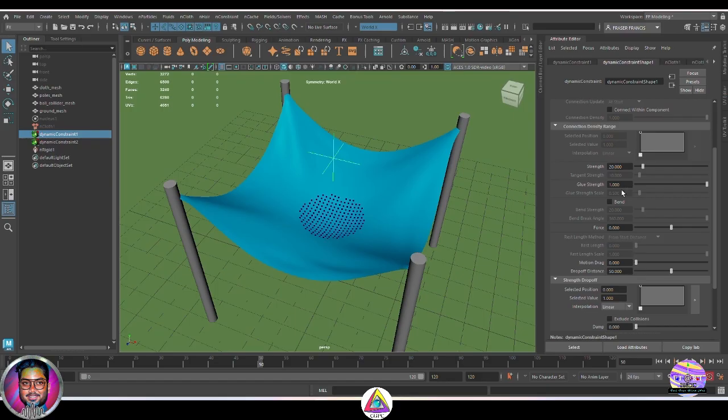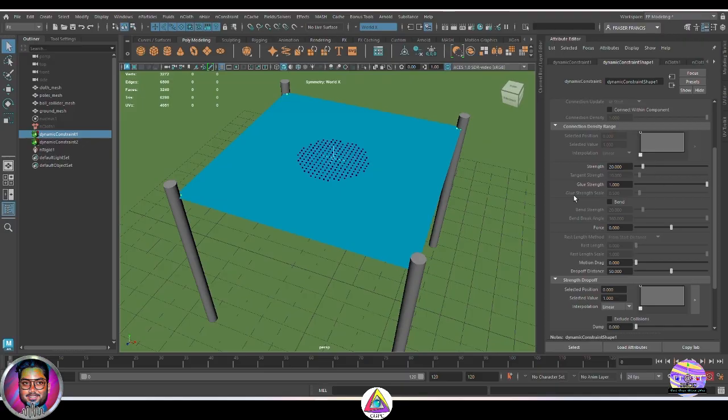So currently it's 1 for the rest of the cloth, which is not going to tear apparently due to its glue strength. Now, if I just go back to the first frame and try to change the glue strength, currently you can see the glue strength scale is not highlighted and not selectable, since the value of your glue strength is 1. As soon as we change this value, let's say to 0.5, the glue strength scale value becomes selectable or editable now, right?